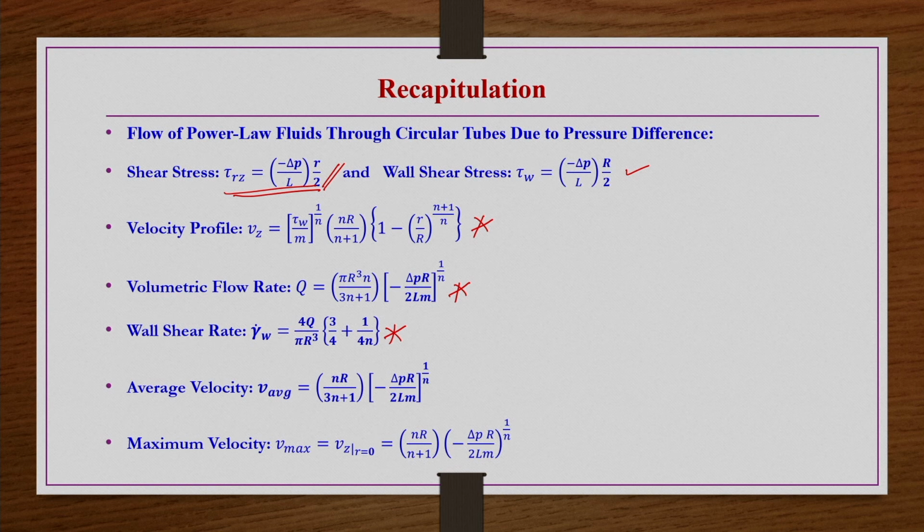But whenever there is a fluid flowing through pipes, what is the important engineering property that you would prefer to measure, especially when there is only momentum transfer? It is the pressure difference or pressure gradient versus volumetric flow rate information.